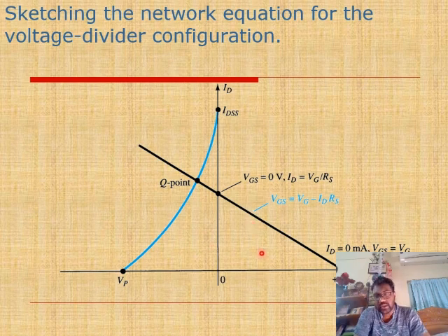It is on the positive side of VGS, but in a JFET there is no positive axis for VGS, meaning there is no operation with positive gate to source voltage. That's why we only talk about this portion of the graph where the Q point is situated.